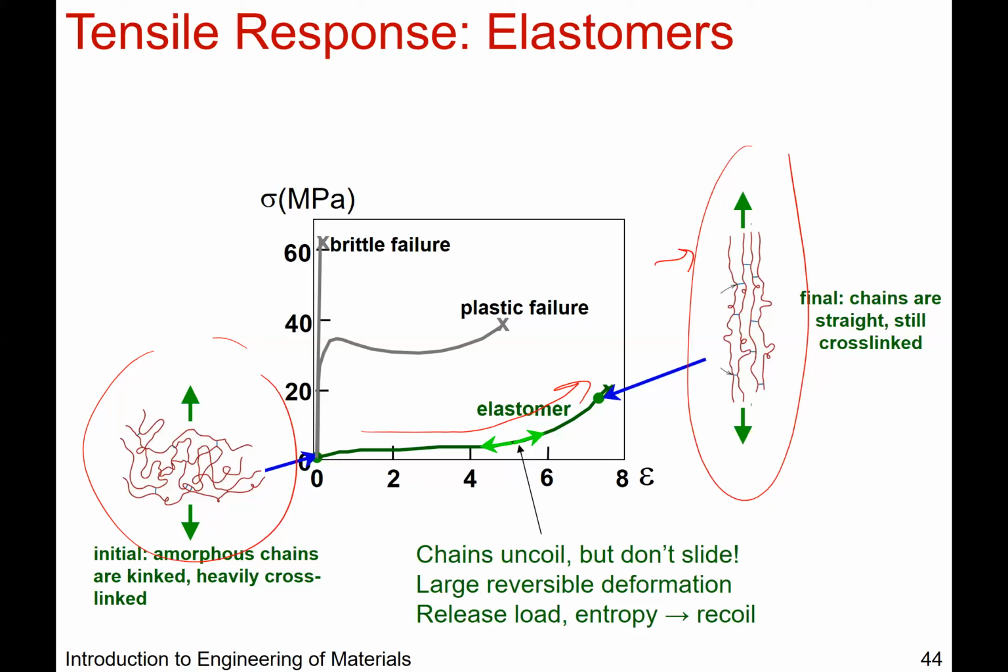Then you ask yourself, is that the entire curve, the elastic region? And basically it is. It doesn't behave in the same way as metals or ceramics. It's a whole different regime. So basically we say it's all elastic and there's really no plastic deformation, because that's going to occur when you snap the rubber band, basically.